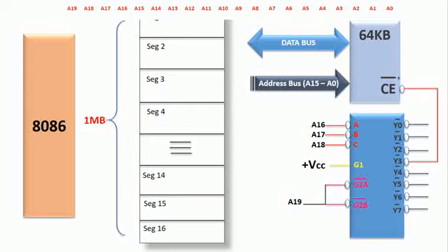In this case, in order to enable the chip enable signal, the rest of the concept is the same, but here the connection is changing, from Y0 to Y3. So in order to choose Y3, what should the input combination be? The input combination should be 1 1 0. You are supposed to apply 1 1 0 as an input to the A16, A17, A18 or the ABC input lines.